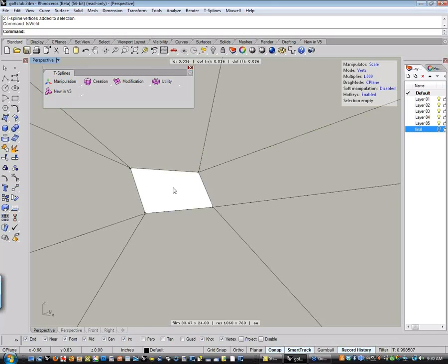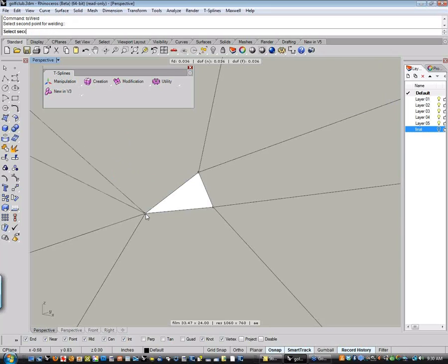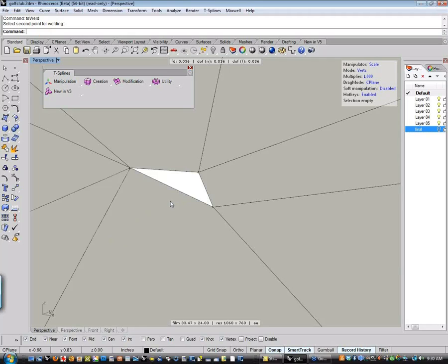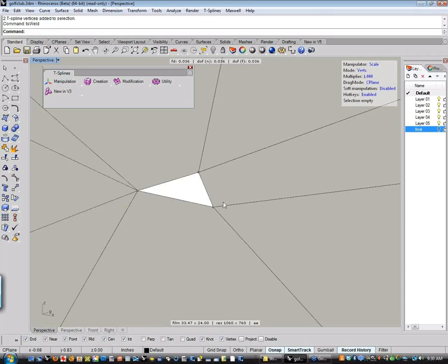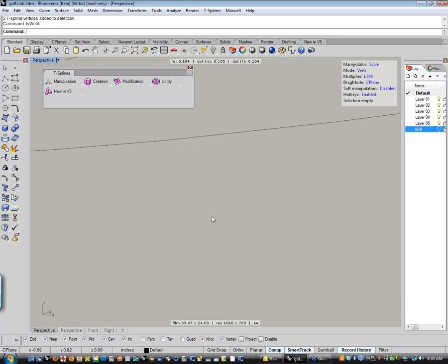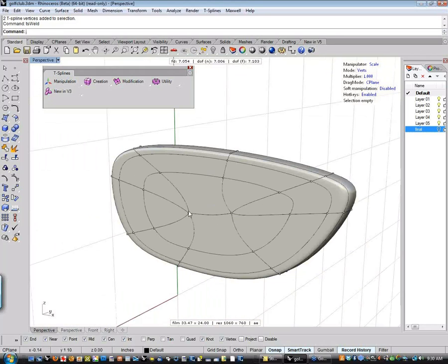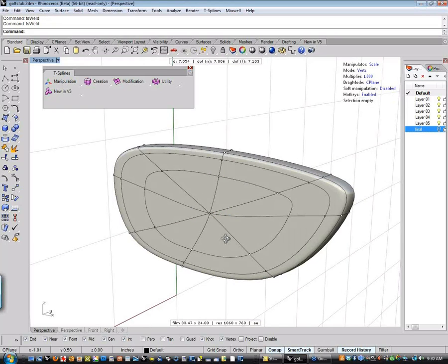So I've got 4 verts left. Well, let me show you a cool trick with the weld tool. Since I'm going to use the Z key for welding, or I can use the button, if I pick this vert first, hit the Z key, and then pick this vert, notice that it jumped from here to there. If I pick this one first, hit the Z key, and pick that one, it jumps from the bottom to the top. If I pick them both and I hit the Z key, they jump and they meet in the middle. That's a cool trick, because if I'm going to pick both, I'm going to have them meet in the middle, and then I'm going to pick this one and this one. I'm going to Z key again, and I'm going to have them meet in the middle,